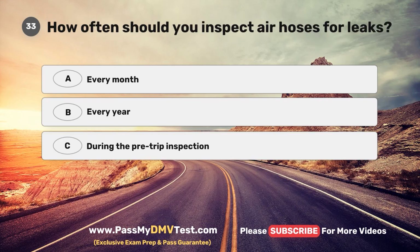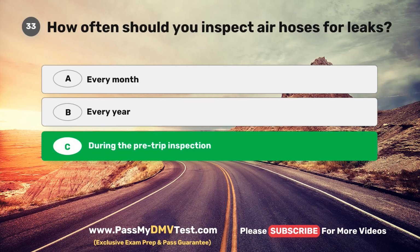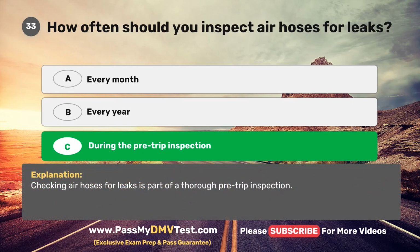Question 33. How often should you inspect air hoses for leaks? A. Every month. B. Every year. C. During the pre-trip inspection. The correct answer is C. During the pre-trip inspection. Checking air hoses for leaks is part of a thorough pre-trip inspection.